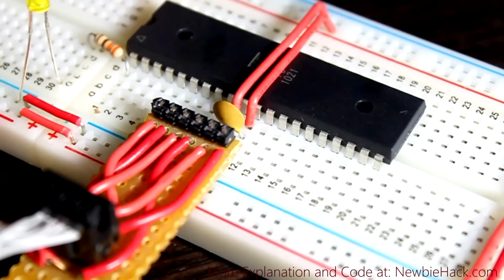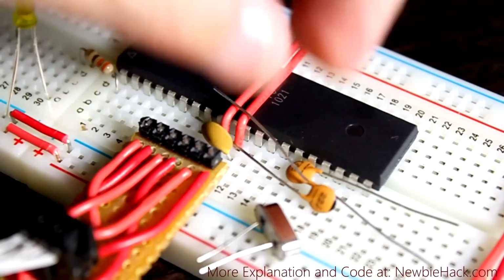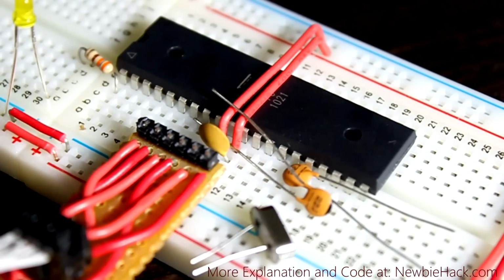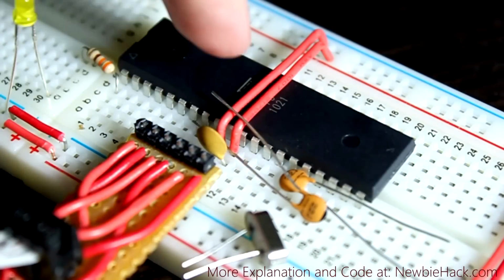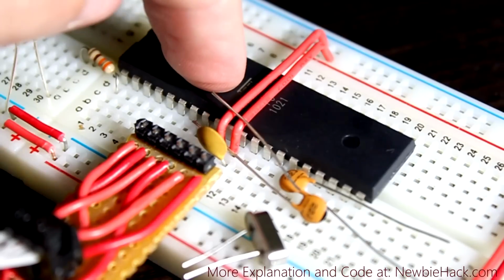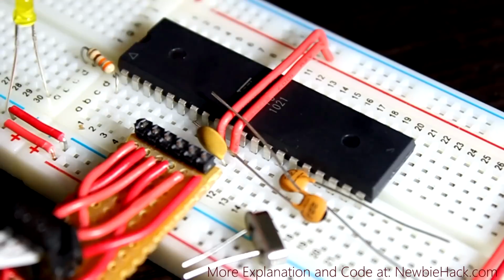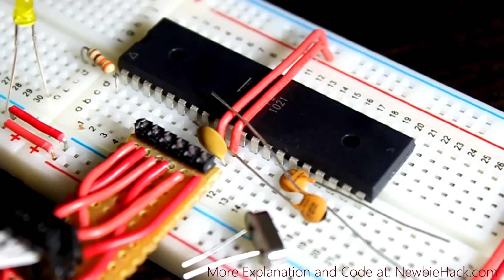Okay, we're going to add the crystal and the capacitors to the pins 12 and 13. Obviously, we can't run it until those are plugged in because what we've done is we set the fuses so it cannot use the internal oscillator anymore. And now it has no clock signal to use as a way to function or carry out instructions.